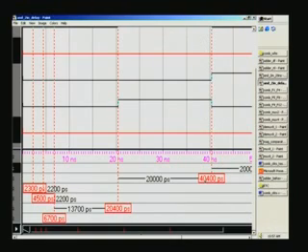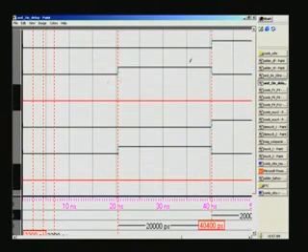And you can see once again the next transition also is staggered, because the very first thing was 20.35. Thereafter it was maintained as 20 nanoseconds. So it's a relative thing. Automatically everything will be displaced by that 20.35, which the system will actually interpret as 20.4. And mind you, all these timings do not appear in synthesis, because in the design you are not supposed to give any timing as such. This is exclusively for simulation. Otherwise the functional aspects are all precisely the same throughout.